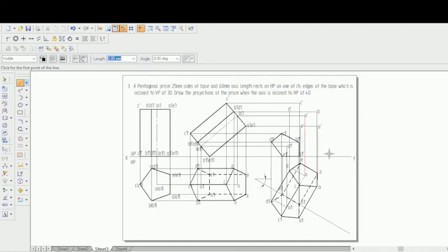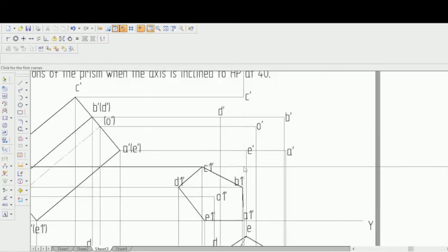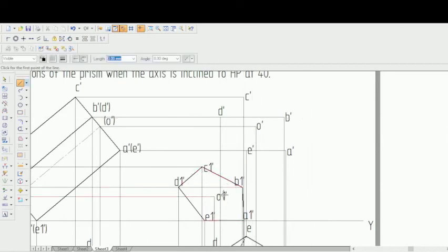Another thing which you will have to see is whichever line is coming from this reference frame, the lines within this reference frame will actually be made hidden. Lines coming out of this reference frame will be made visible. Now let's try to draw the outermost points. The outermost points are the boundaries. So D1 dash to D dash, D dash to C dash, C dash to B dash, B dash to E dash, E dash to A1 dash. So A1 dash is here. So that is joined using a visible line.